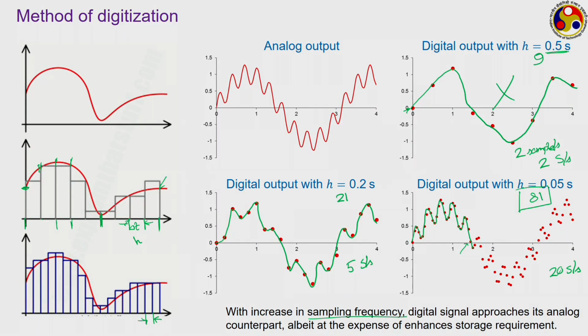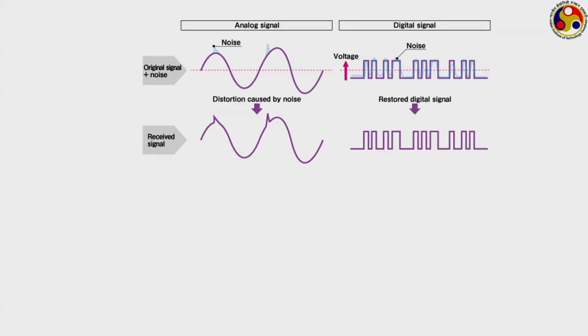So, such accuracy may not at all be required for the application which is of our concern, and hence our choice of the sampling speed, or the number of data points that we can deal with, depends on the application also. But the principle of digitization remains the same. Here, instead of having a continuous measurement, we are measuring the data only at certain time intervals. This is one advantage for digital signal over analog.